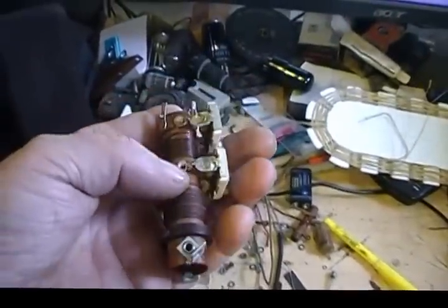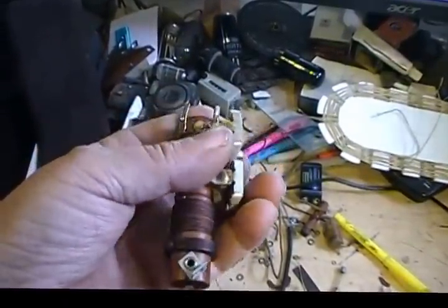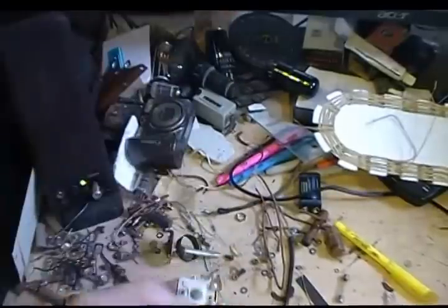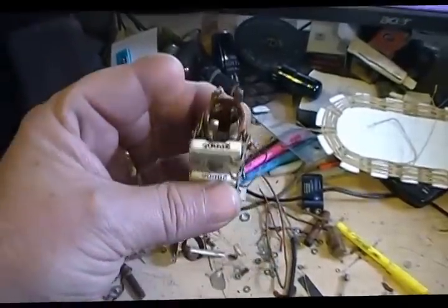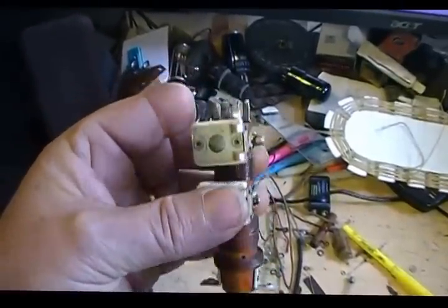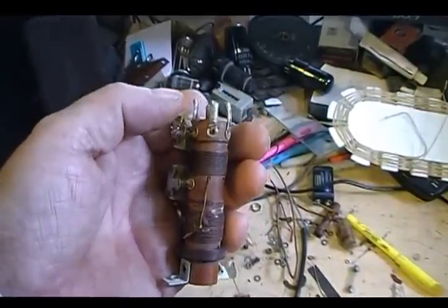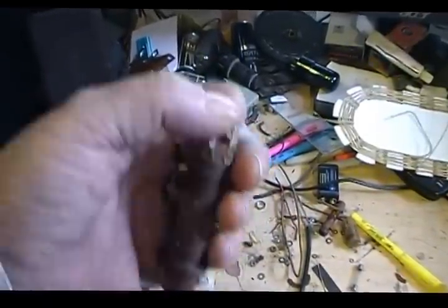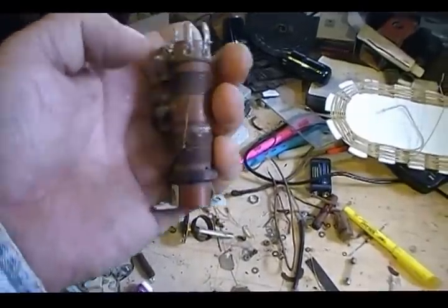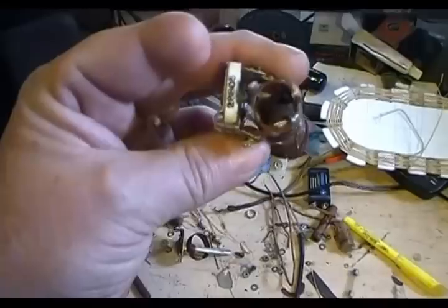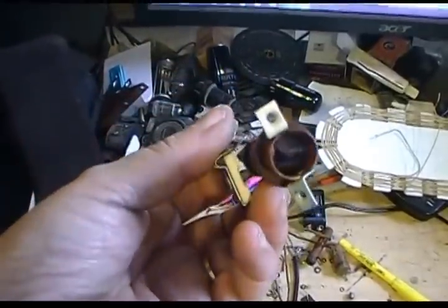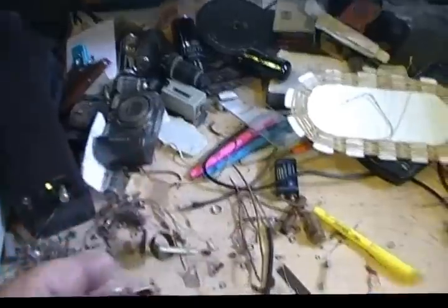And that'll help you where the windings hook up to, because you know that they hook up. You can find them in the schematic. They're labeled and everything. So once you get to that point, you find your common points, you know where they hook to, then the other points are a lot easier to locate, and you can locate those by just looking down through the coil, maybe taking some measurements and stuff.